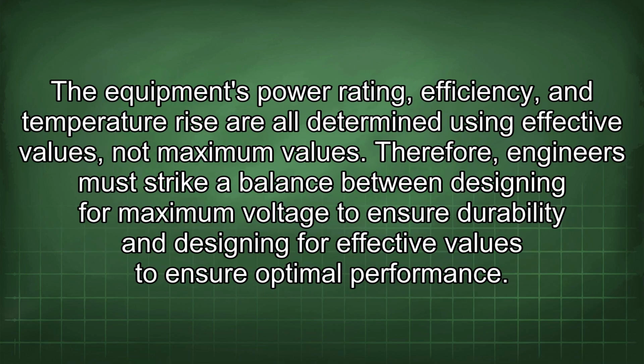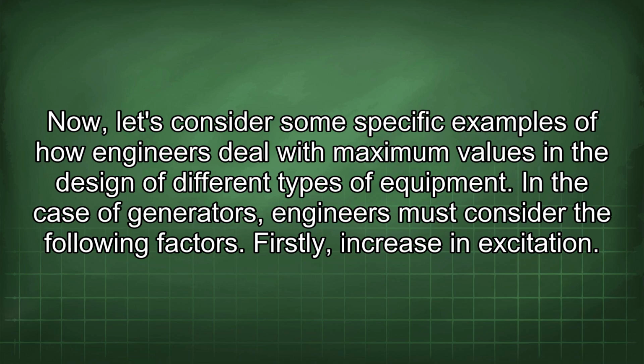The equipment's power rating, efficiency, and temperature rise are all determined using effective values, not maximum values. Therefore, engineers must strike a balance between designing for maximum voltage to ensure durability and designing for effective values to ensure optimal performance.